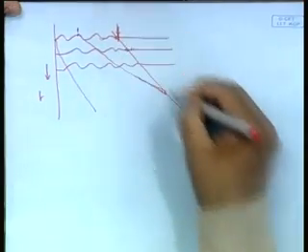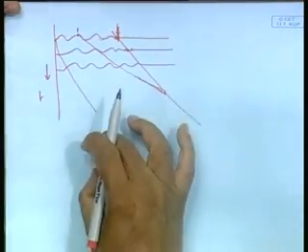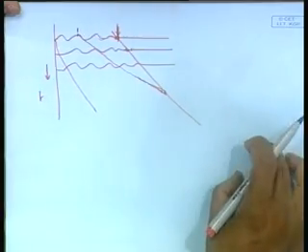Where does it relate to my ship motion? We will find out that yes, there are very good applications of this eventually when we talk about ship motion. For example, even earlier we have seen in wave resistance that the energy propagation is extremely important, because if the energy was propagating at the same speed as the ship, then you end up getting a very large resistance, energy getting trapped, just like in the sonic boom case of aircraft. Similar things would occur in ship motion also, in the spectrum when we get to that. So, energy relations become very important.